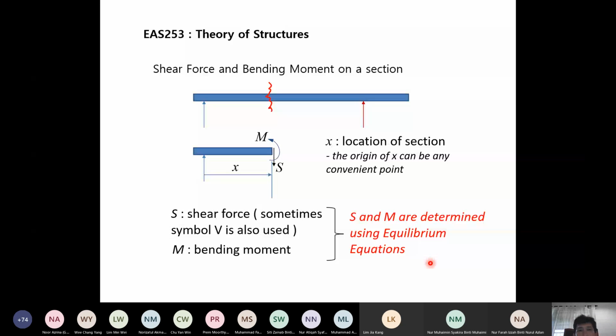So this is what getting shear force and bending moment involves, the work. Know where the section is where you want to determine the internal force, draw the appropriate free body diagram, either the part on the left or the part on the right, and then after that indicate correctly the shear force following our positive directions, following the sign conventions, and be clear about where the section is.